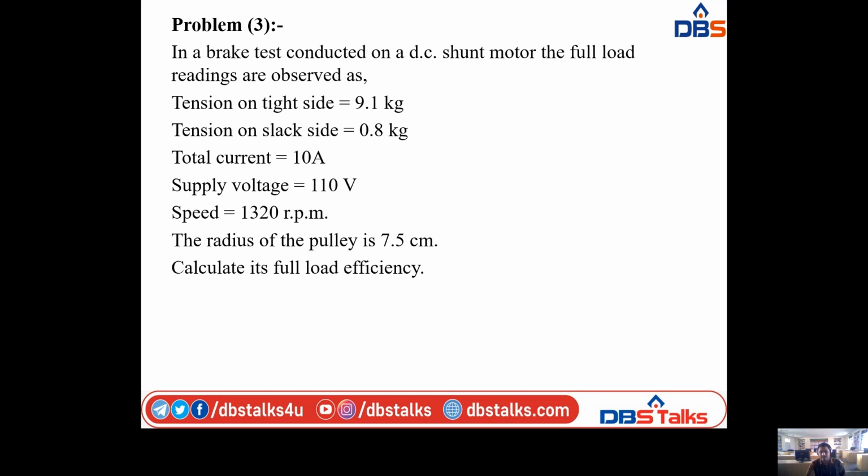And on the right side we have the generator. So here the generator also consists of the armature winding and field winding. So here the field winding is connected to the motor, generator field winding, and next the armature winding consists of the ammeter. So here the generator current is 32 amperes and it consists of the voltmeter, that is voltage across the armature, that is 160 volts, and finally it is connected to the load. So this is the diagrammatic representation.